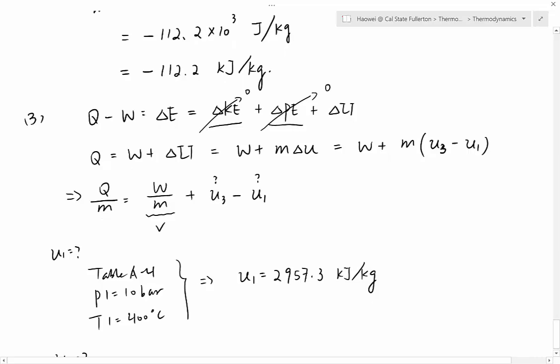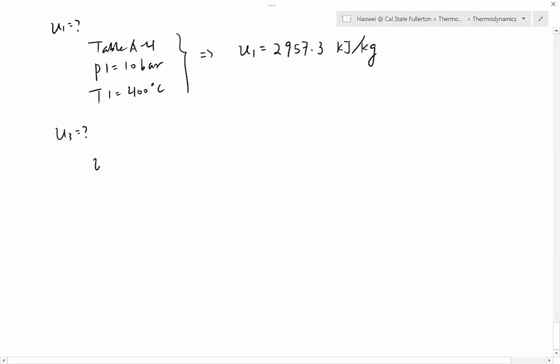Okay. So now, if it is a mixture, how do you look for U? We gave you this equation earlier this week. If you have a mixture, you have to use the equation to find the corresponding U. All right, can you memorize this equation? U3 is a mixture. It has 2 components. The first one is the saturated liquid. You can call it U3F. The second component is saturated vapor, point G. So for this one, we call it U3G.